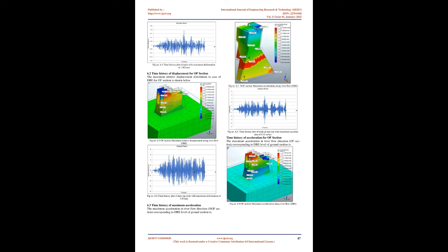The modal superposition method and direct method are used for linear time history analysis. The mode superposition method assumes the structural displacement as a linear combination of orthogonal displacements. Using this, a more simplified time integral function can be used to calculate the dynamic response for a selected mode.